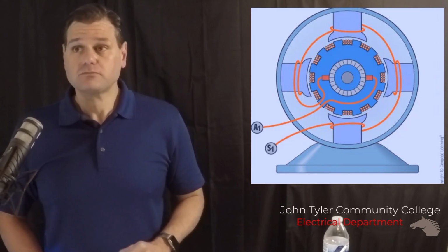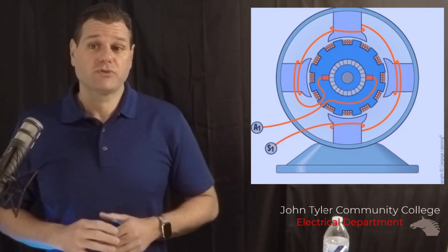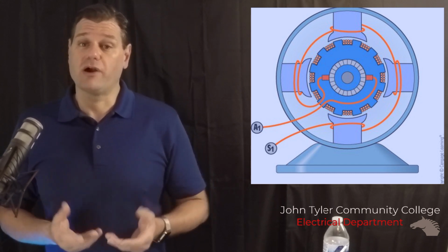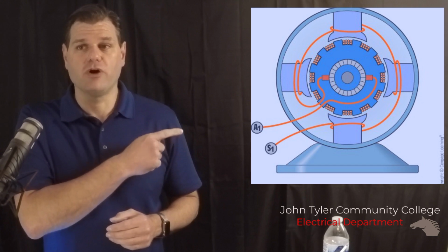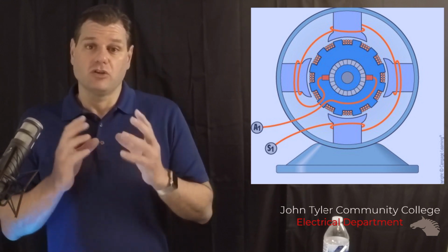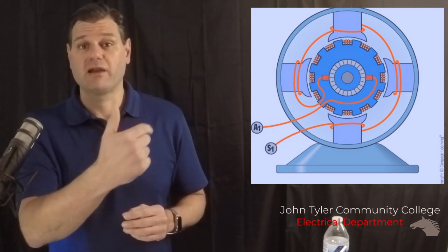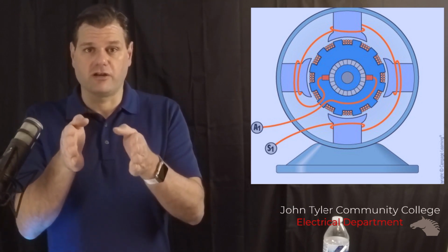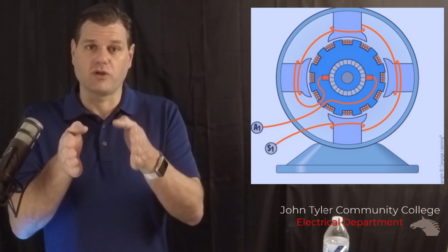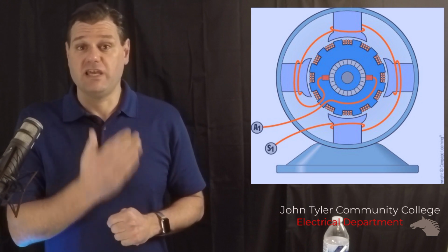Okay. This particular winding here is our series winding. So our series winding, again, is the heavier wire, fewer wraps around the pole pieces. And you can see that we go in as A1, straight into a brush. The brush goes into the commutator, goes into the armature windings, and then comes back out on another commutator plate, usually 180 degrees off from each other. So one's on one side, one's on the other. It's going to leave as A2.